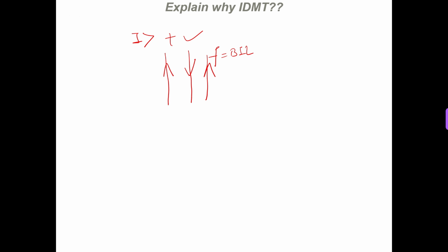Depending upon the intensity of the magnetic field and the amount of current, we will have a force acting on these conductors, and depending upon the direction of these conductors with respect to the magnetic field, these forces on the two conductors could be attractive or repulsive, and this may damage these conductors. So every equipment has limitations, that it can sustain a certain limit of current above its normal rated current for a certain amount of time.